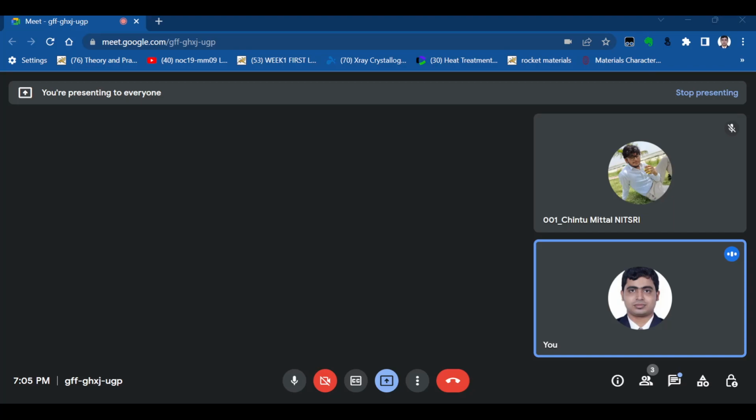This is same for both cases. This is also same. So if this is larger for X, then this A should be also larger. So material X can withstand larger flaw size. Alloy X. So this one component made from alloy X can tolerate a larger flaw size compared to that made from Y. This will be the right answer.